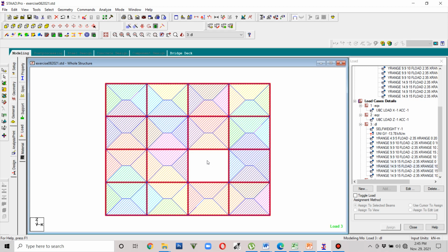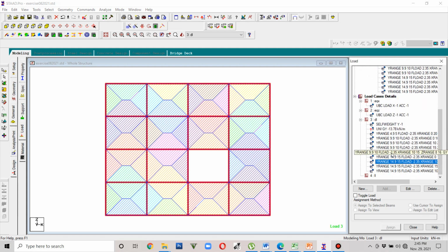So we have assumed that this portion is an open or stairwell, no? An open below flooring. So walang flooring dyan. So anyway, that's the purpose of having a range. Okay, using range. Unlike yung ginawa natin before, that we have grouping, we cannot really delineate the flooring with the opening, no? Okay, so we have a conservative approach on that one, wherein all of the flooring are having slab or covering.